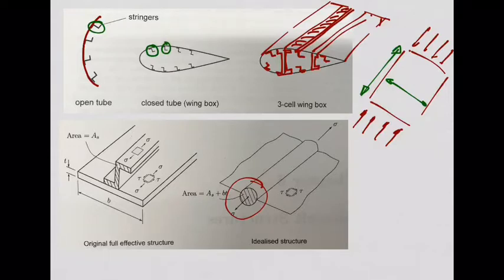And also on top of that, once your FEA model gives you good results, for Airbus, they also do experimental testing. They put the full wing in a huge rig, and they apply the full loading. You can see that on YouTube. I think maybe next week I can bring a movie, just to make a different lecture, to show you that test being done on a wing, right? So you have to do all this kind of testing. But this idealized structures approach, in practice, is being done especially in the initial iterations of the design process. Okay. All right.